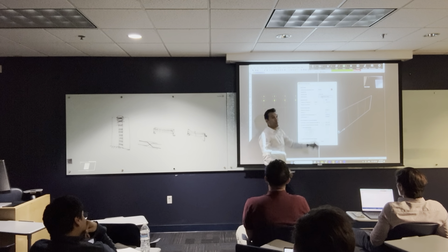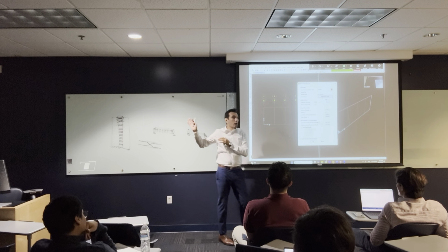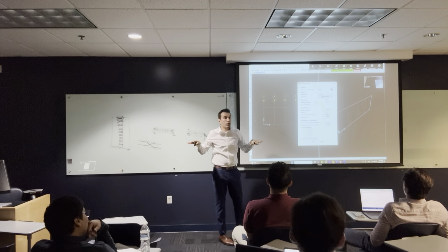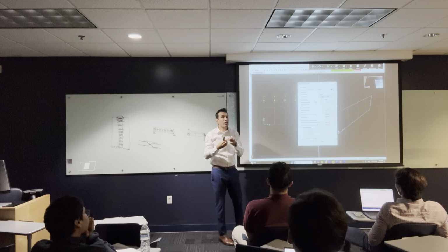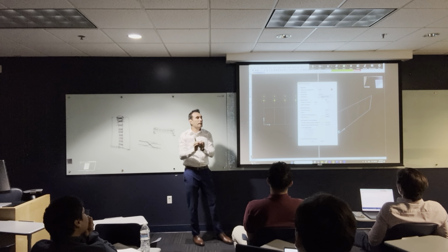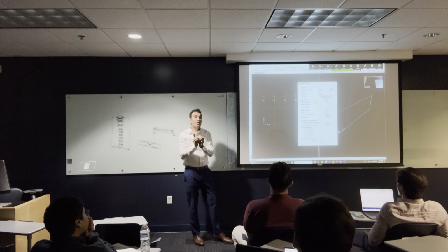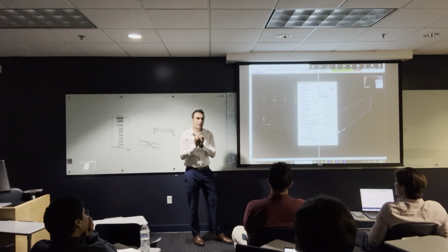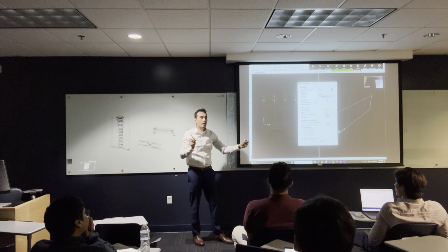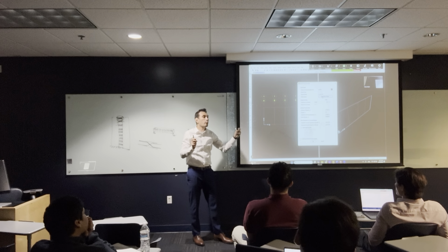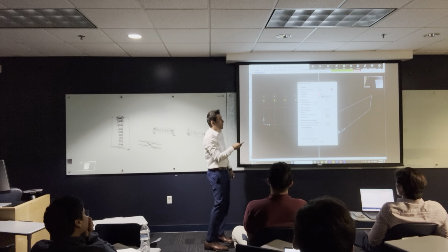You can actually make the name of the material Omar, or you can make it green. You can make the material whatever name you would like. But we would rather name the materials with unique names. What is the unique name? What is the unique characteristic of this concrete? It is the characteristic strength, the compressive strength of the concrete, which is 4,000.